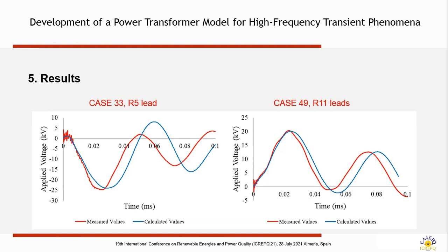Results can be improved by reviewing the capacitance calculation, especially for the interleaved winding, which was the high voltage. Normally, in the capacitance calculation, you try to be conservative, but in terms of amplitude. But in terms of phases, you don't pay a lot of attention to that.